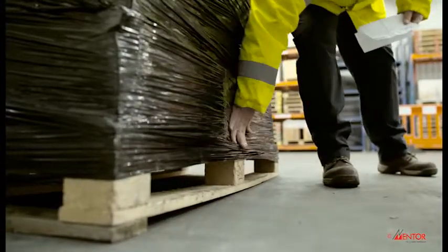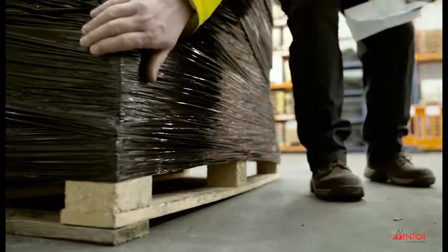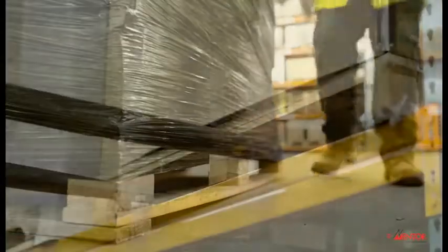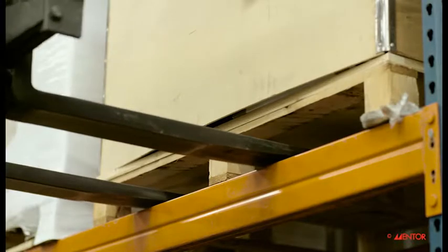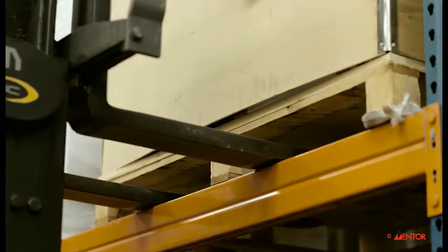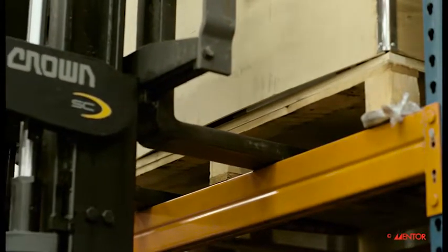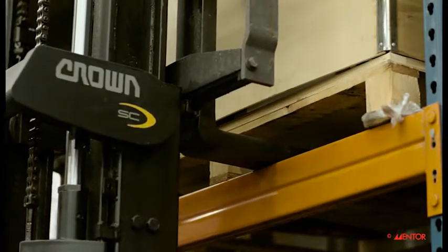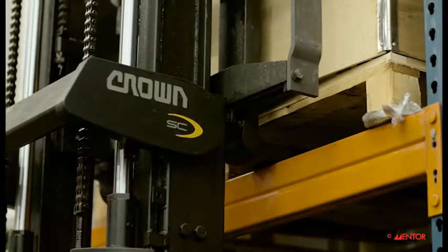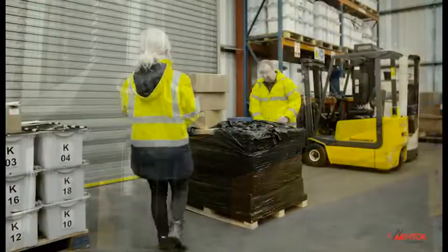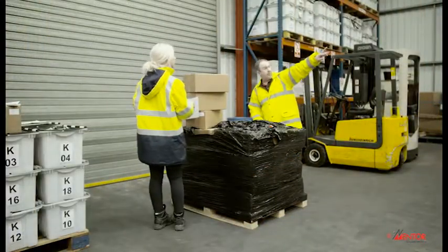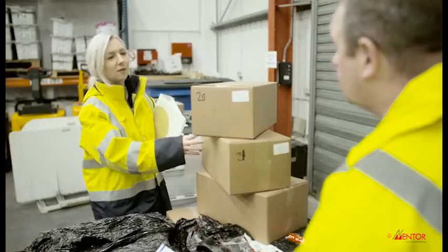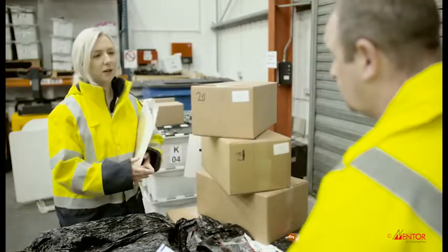You must also check the dimensions of the load to make sure it's suitable to transport and can safely be unloaded. Make sure that the load is fully heeled, with back tilt applied, and that the forks are not too long and protrude, as this may cause adjacent loads to be dislodged when stacking. As a pedestrian, for your own safety, you should report any load that looks unstable to the driver and your manager.